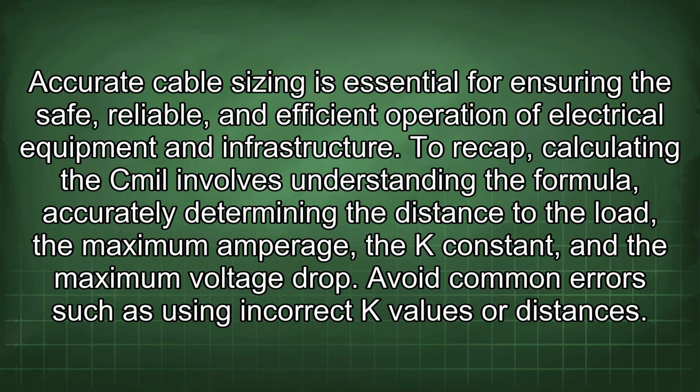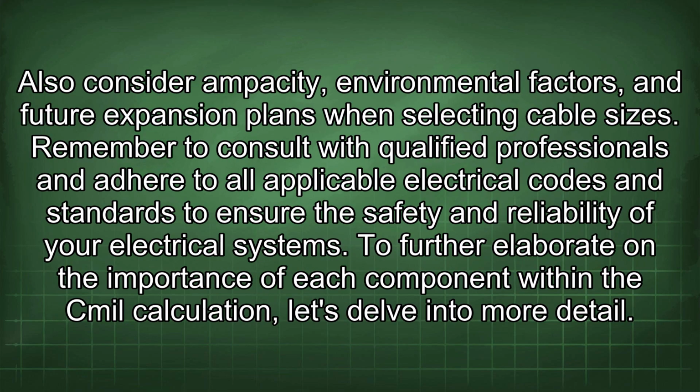To recap, calculating the Cmil involves understanding the formula, accurately determining the distance to the load, the maximum amperage, the K constant, and the maximum voltage drop. Avoid common errors such as using incorrect K values or distances. Also consider ampacity, environmental factors, and future expansion plans when selecting cable sizes. Remember to consult with qualified professionals and adhere to all applicable electrical codes and standards to ensure the safety and reliability of your electrical systems.